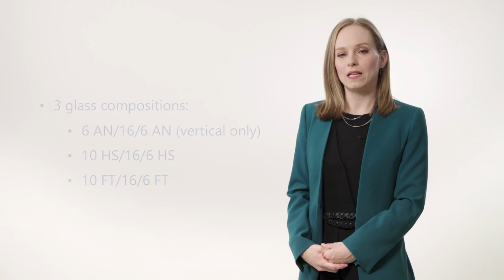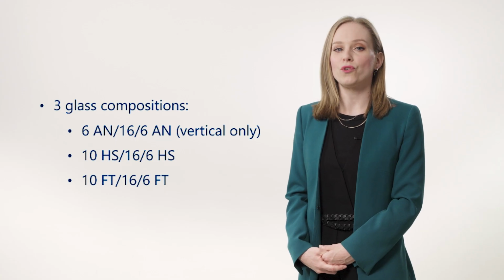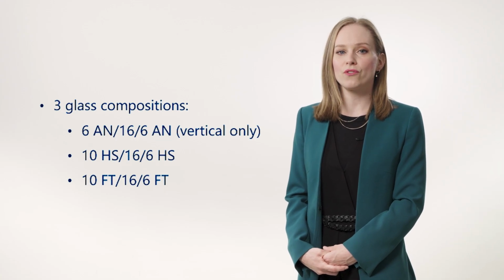All verified units are composed of two monolithic panes. For the clarity of the procedure, laminated glass is not considered. The only comparison criterion is the minimal thickness of the glass required for the load-bearing resistance. The calculation is carried out on 3 different common glass compositions, and for each composition there are 3 different glass dimensions. In 2023, the final draft for Eurocode 19100 was released.